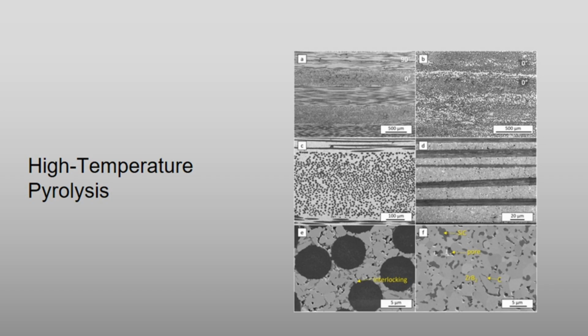High temperature pyrolysis. The green body is shifted to an oxygen-free retort furnace under an inert gas, argon or nitrogen blend. The temperature is ramped up to 900 degrees Celsius to 1200 degrees Celsius, causing organic molecules to volatilize as exhaust gases, leaving behind a hard inorganic silicon carbide ceramic matrix. The high-resolution microscopy view shows how multiple infiltration cycles gradually seal, densify porous matrix areas, and interface with structural fiber bundles. Step 6. Densification loop.